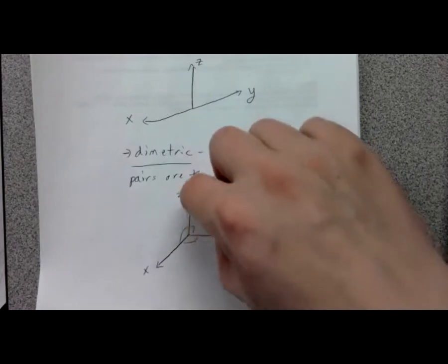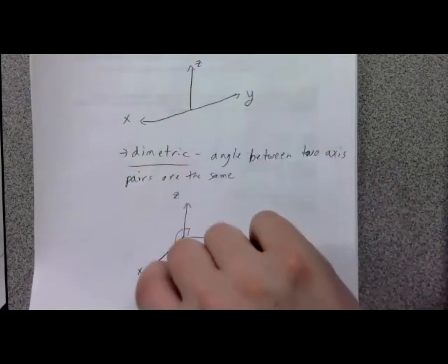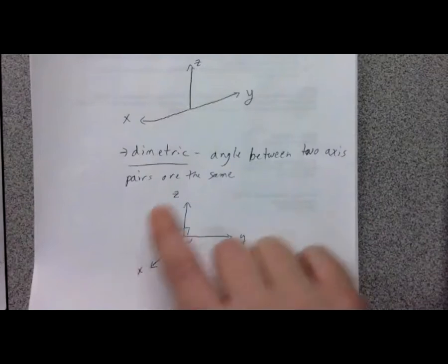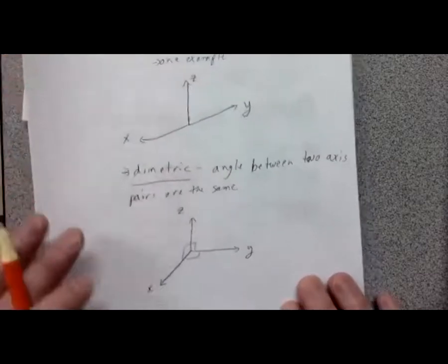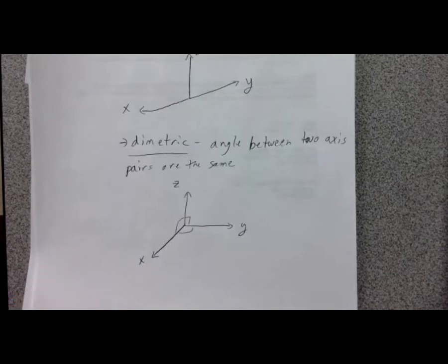It's dimetric. I could squeeze this down, make this 80 degrees, and then make both these 140, or whatever adds up to 360. As long as the sum of all angles adds up to 360, you're not violating any rules. That's a common way to do dimetric, especially if you're on grid paper or just freehanding. I highly recommend that.